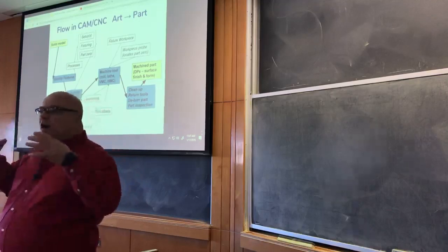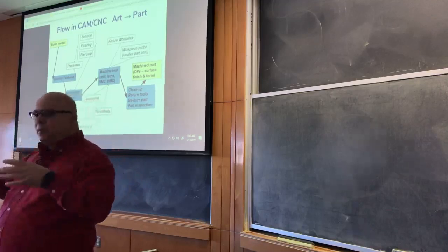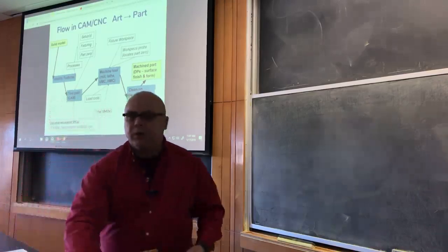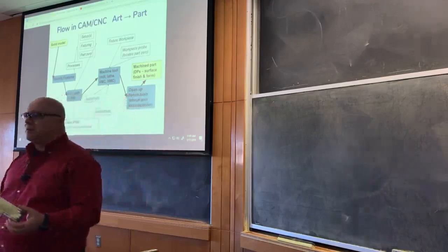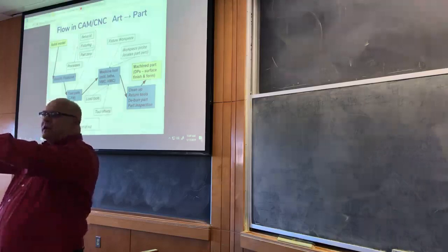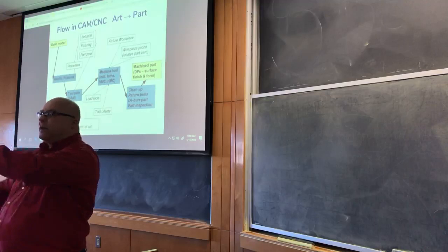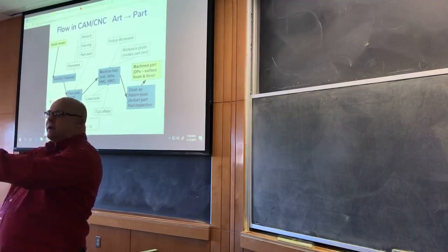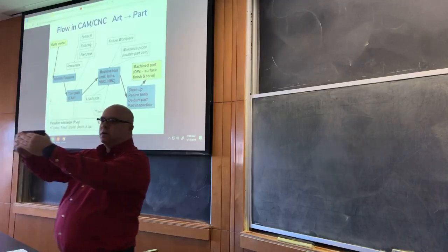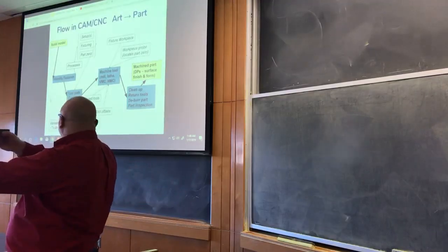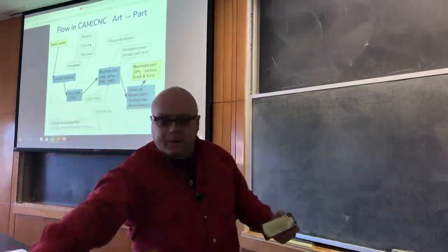Okay, so Mike, our CNC machine tool, if we've got our part fixtured in a, here's a part. Sorry, do we fixture the part or the workpiece? We fixture the workpiece. We've got our workpiece fixtured in the CNC machine tool. Assuming that I'm standing and aligned with the Z-axis here, what kind of features can I make on this part, if I've fixtured it like this in a vise? Let's quickly draw what I'm talking about.